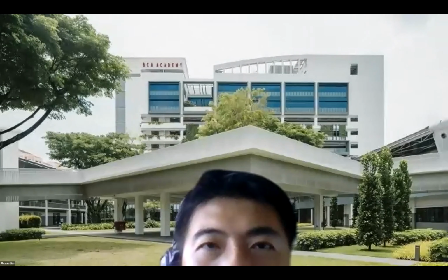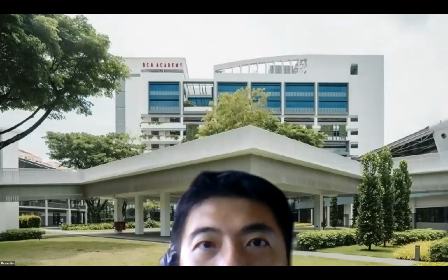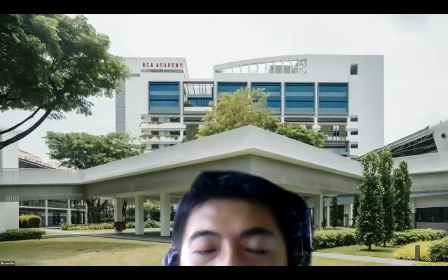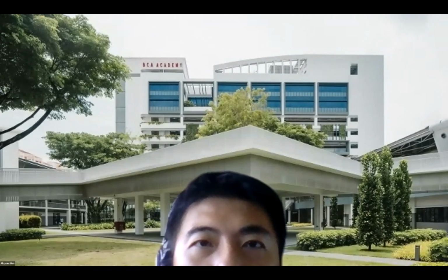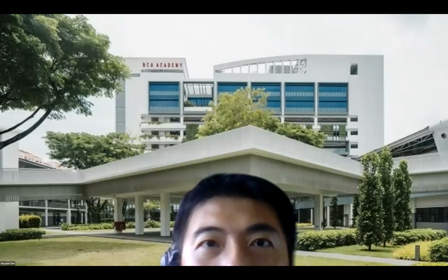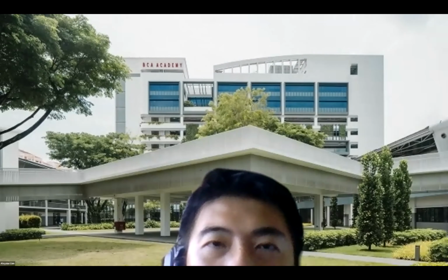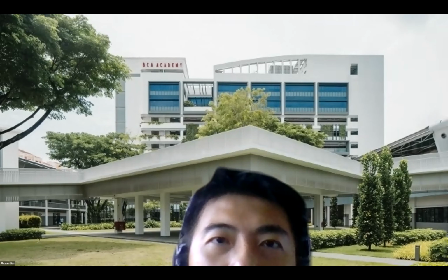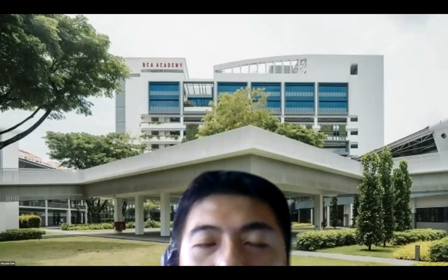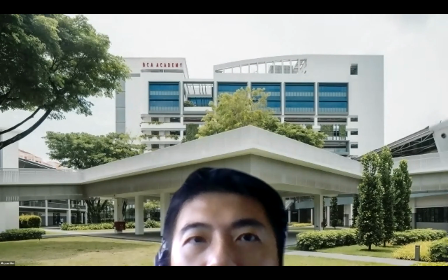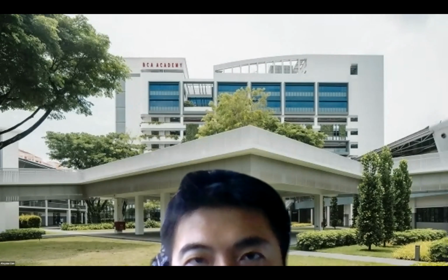Again, there will be someone who is more adept at computational BIM tools like Dynamo, then they package it to become a Dynamo Player. So this Dynamo Player is very easy to use. It's just a software plugin within the Revit interface. They just press play and play around with the slider bars to maybe generate how many light fixtures you need in this room. It will automatically put this out for you.